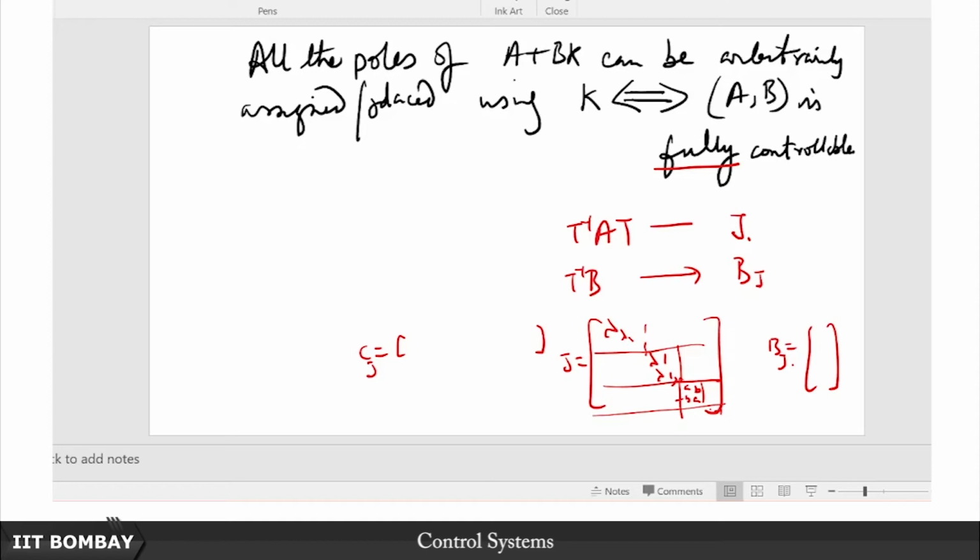So that is precisely the point of saying it is fully controllable. When we say it is fully controllable, it means every state can be independently maneuvered. In other words, remember these are the eigenvalues after all, and every eigenvalue can be given a nudge or pushed through the input. So fully controllable means every eigenvalue can be shifted, so it makes sense to say all the poles can be moved.